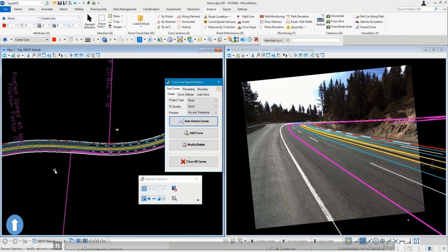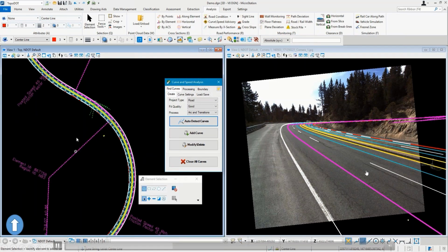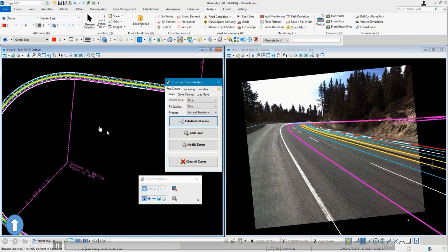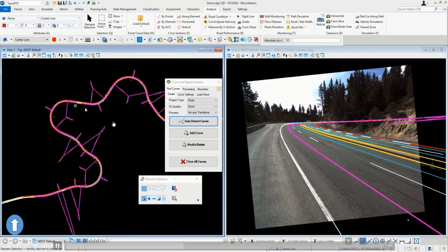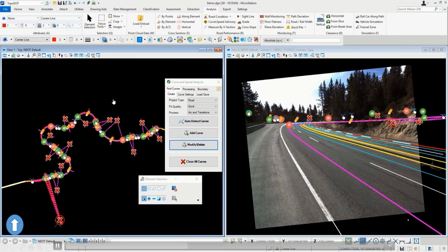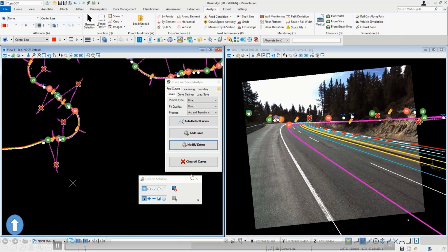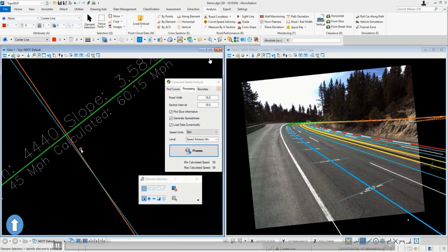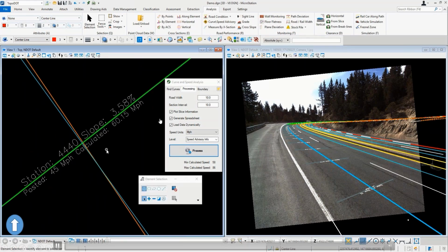We have a line down the center of each lane. That's very easy to do. We have to extract the lane lines. And then we'll identify the radius of curvature plus the spiral tangents, everything like that. Everything is done. There it is. These are actually individual elements that can be exported. And if I go to the end, I can actually give you the slope here and the speed advisory along this corner too. There's all kinds of things that are being done.